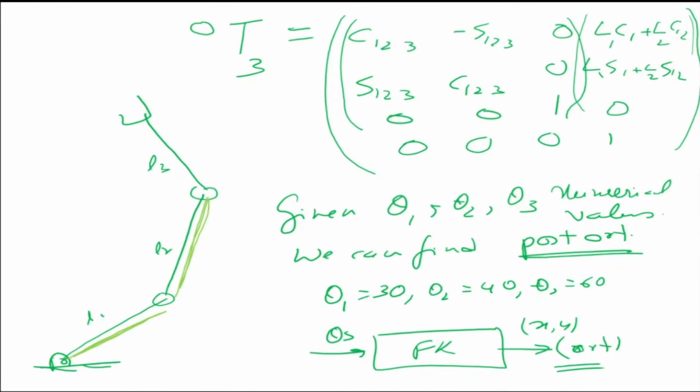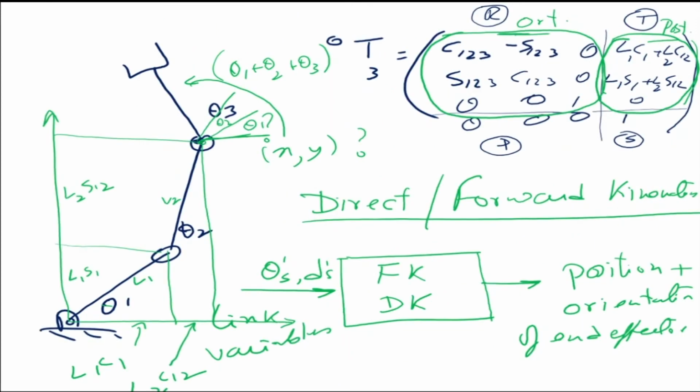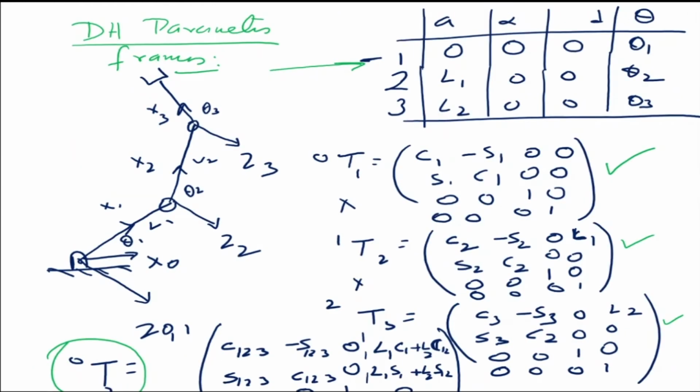So whatever is coming from here in terms of the matrices, let's look at the matrices again. If you look at the first matrix and the second one, and the DH parameter table here, they are exactly the same. You should be able to correlate this and understand the relationship between the matrix and the manipulator when it is moving in space. So this is a SCARA robot, which from the top view appears like a 2 degree of freedom arm. The DH parameter table for the first two joints is the same. The third joint is a prismatic joint which is moving perpendicular to this joint.